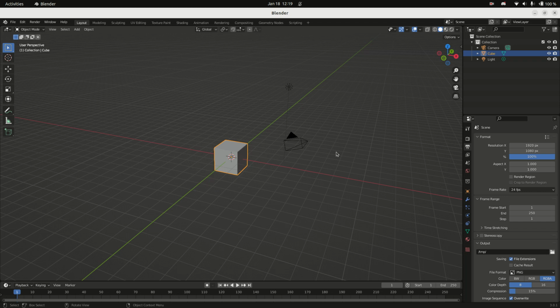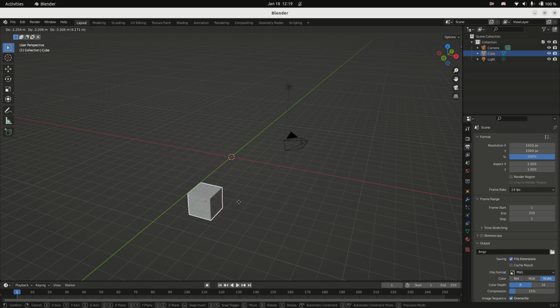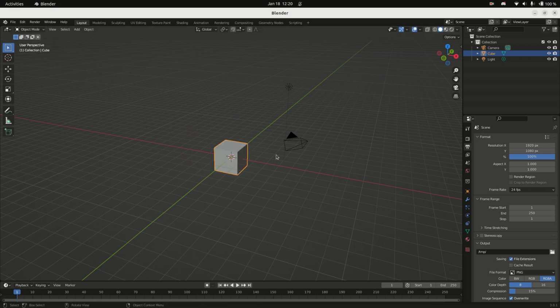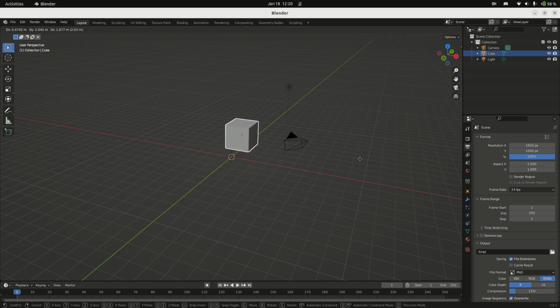Now if I want to move something around, I can grab it with G to grab. And again, I'm moving it in the plane described by how my viewport is seeing things. So you can see my X, Y, and Z in the top left corner up here. Oh, no, I can't. Let me cancel that. This gets replaced when I hit rotate with how many degrees of rotation. Or if I'm grabbing, the delta X, delta Y, and delta Z of the position of the object.